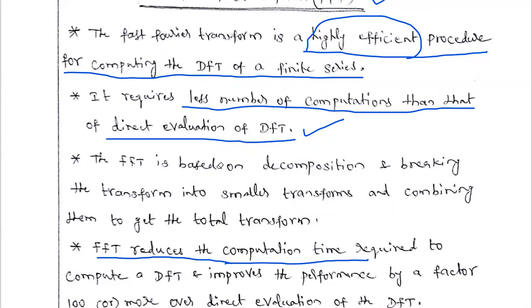Okay, so that's why the FFT is based on decomposition and breaking the transform into smaller transforms. That is, the 16-point DFT is first divided into two 8-point DFTs. Then each 8-point DFT is again divided into two 4-point DFTs.